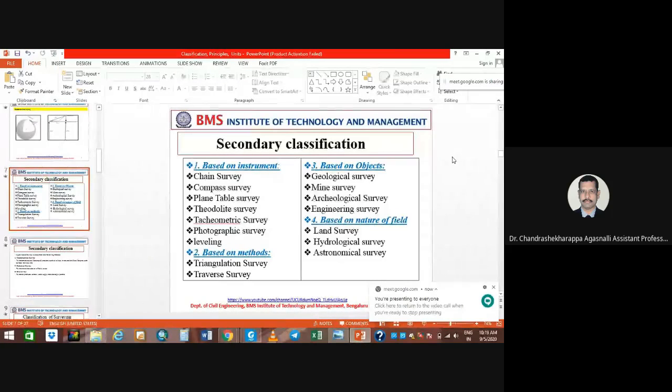Which instrument can you use? Theodolite. Yes, that gives horizontal measurement angles. You can do the plane table survey also, but it takes time. Generally we avoid the plane table survey, because setting up the plane table takes time.